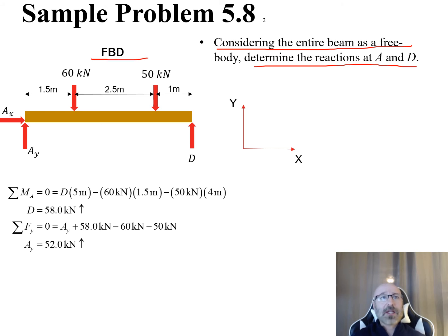So for our free body diagram right here, here's our beam AD right there. So we can see, well, we have our reactionary forces here at A, we have a reactionary force here at D. We have the distributed load that's been condensed down now in the halfway mark. So it's in between that 3 meters total. So we've distributed this down. So this is 60 kilonewtons at a distance of 1.5 meters away from our point A right there. So that's something that we were able to find by looking at that distributed load and paying attention to what it was given to us as and where the halfway point is. So that's now how we created that 60 kilonewtons right there.